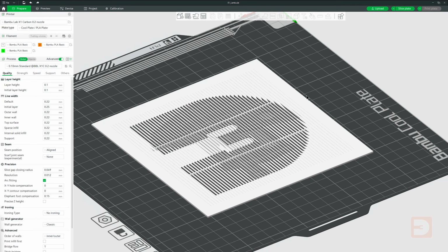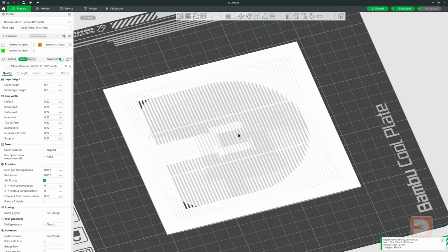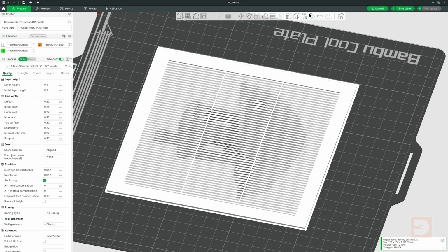But what's also cool is because each image has its own set of faces, providing you set a suitable thickness in Luban for the size nozzle you're using, ideally which would allow for 4 or more lines per vertical bar, you can then paint your individual images different colours, therefore producing a multicolour lenticular print. I find it easiest to do this whilst viewing the side with the straight vertical bars, not the side with the wavy bars, so for now I'll orient it the other way up and slip into the paint tool.